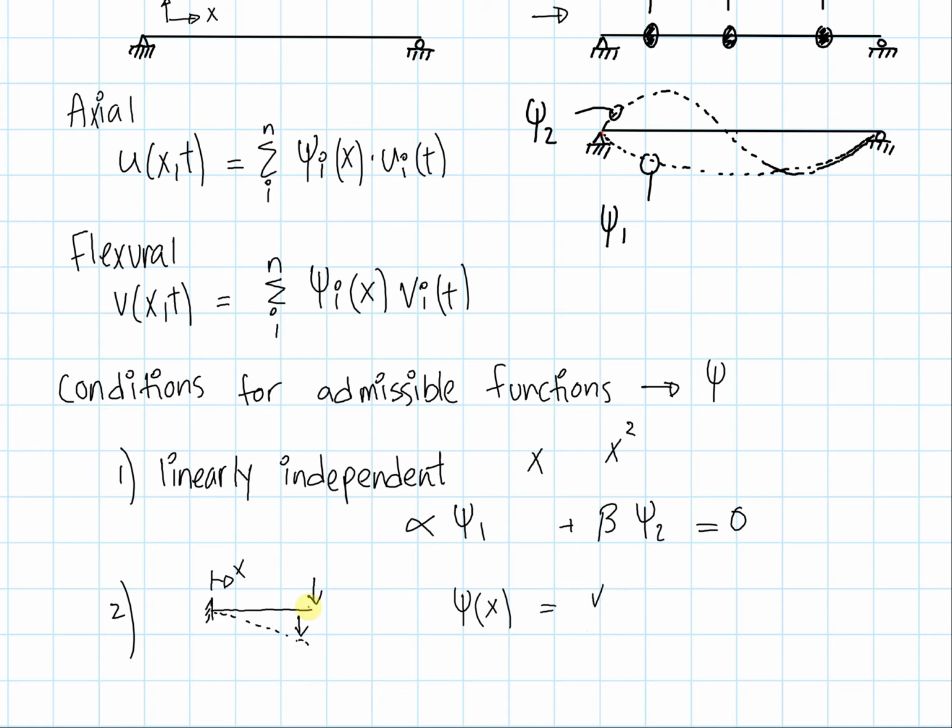Now, when I'm deforming this beam downwards, is it going to have a slope? Yes. Is that slope going to vary with position x along the span of this beam? Yes. So psi prime(x) also needs to be a function of x. Now, the next derivative in this list of strain energies will be curvature. The second derivative, I want to say, is curvature.